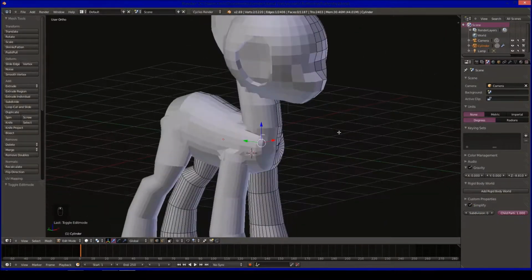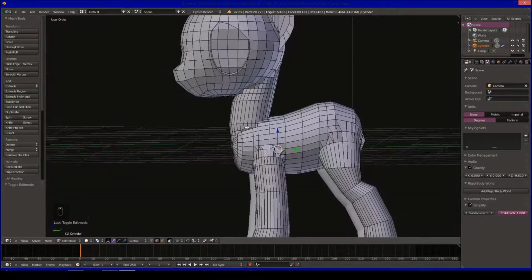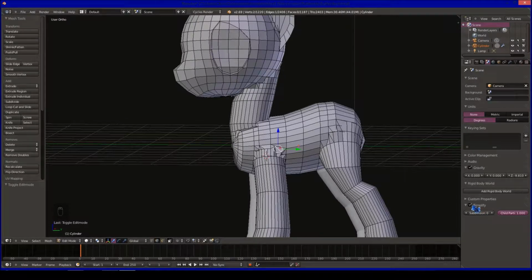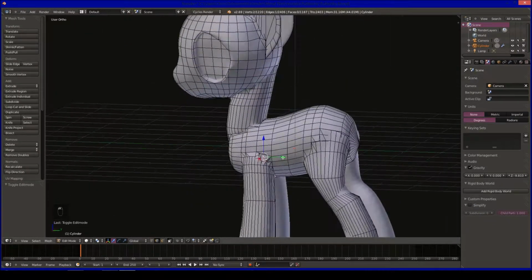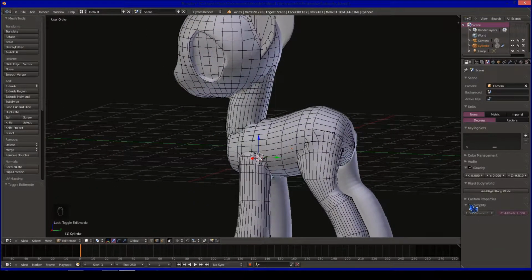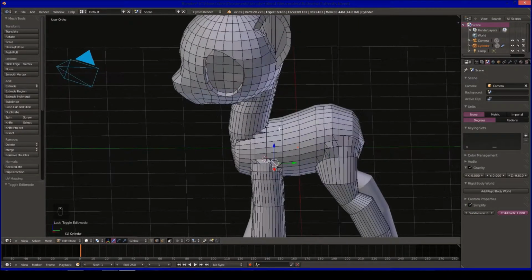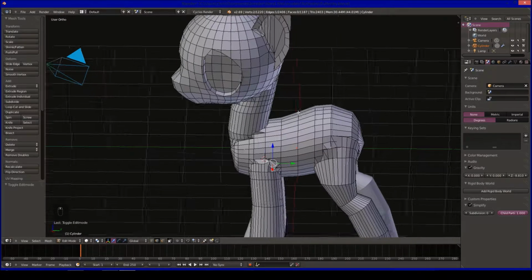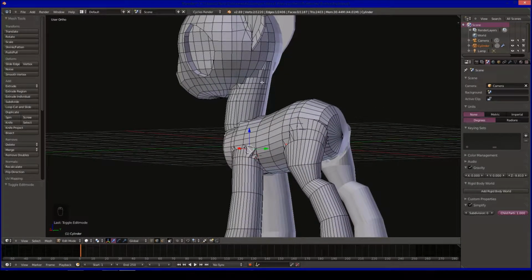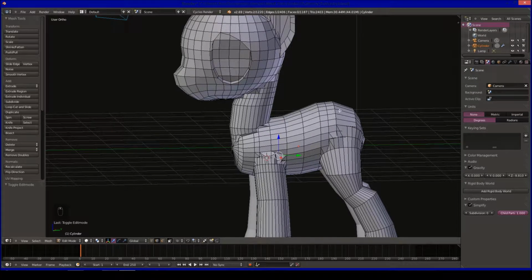And this is so if you're doing animations, it will actually play at the normal speed. I can uncheck simplify and it'll actually go and subdivide everything back to what I set it to. Check mark the box, it undoes everything. Because when you start running several thousand vertices on each model, Blender will slow down a lot.